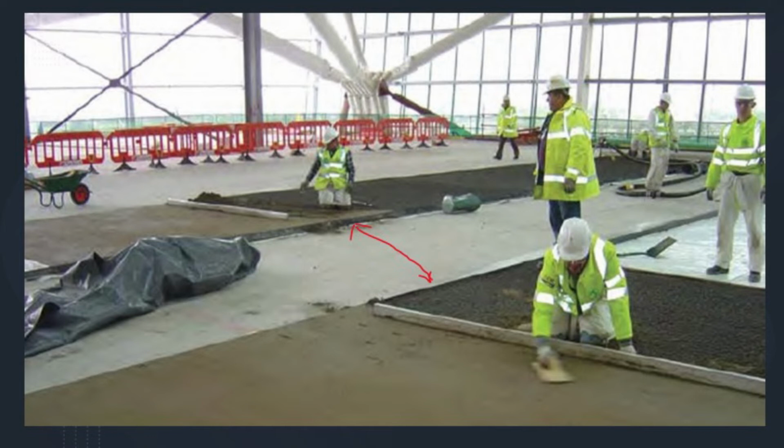The reason is, as the screed doesn't generally have reinforcement, we have to allow it to shrink or set in a day, so 24 hours. Once it sets, the next concrete will be placed to accommodate that width. Otherwise there will be a crack throughout the construction joint.